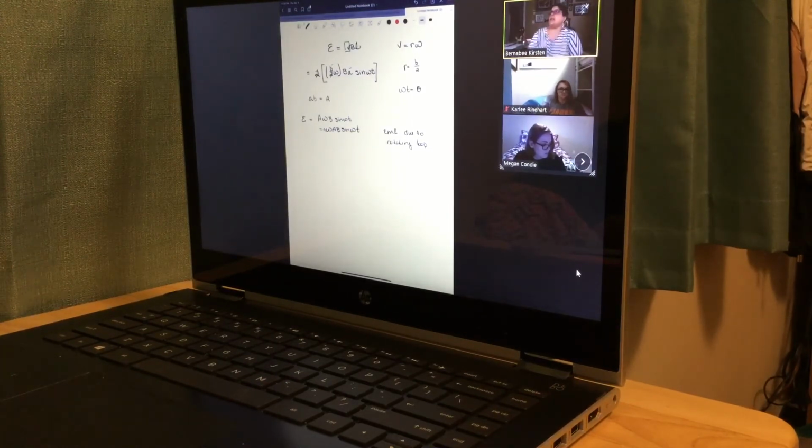This is the basic idea behind an alternator also. So you have a conducting coil, you rotate it in a magnetic field, and it will produce an alternating voltage. Hook that up to a circuit, and then you will have an alternating current as well. Now, one problem that we run into, though, alternating current cannot be used to recharge a battery.